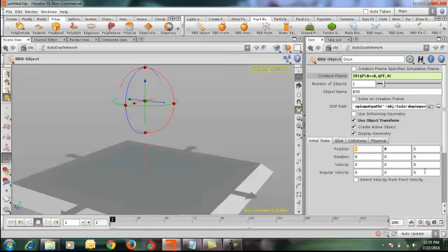Obviously I'm going to randomize, so I'm going to need my random object, and whenever we give a random object, we need to give it a seed value, right? The easiest way of giving a seed value is using an obj. Just take an object from the scene as its seed value. Now obviously I don't want this to take any random number which is not going to fit onto my scene. So I need to limit my random, let's say between -1 and +1.